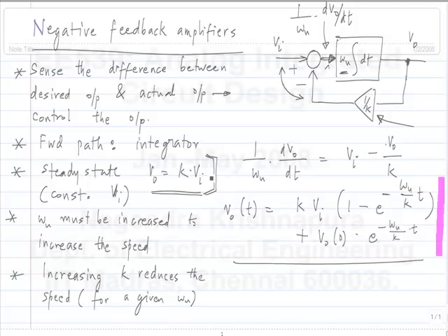How would you go about calculating it? Okay. Yeah, firstly, if somehow we imagine that we don't know what the exact answer is, but the logic he described is correct, that if the input is a sinusoid, and let's say the output is k times that sinusoid, then the difference is 0. So we have a case where the difference, the input to the integrator is 0, but the output is varying, like a sinusoid. That can't be the case, right?